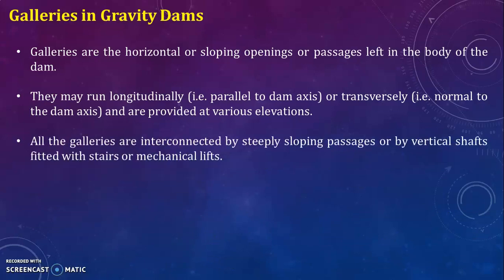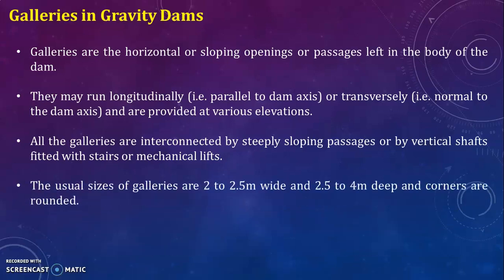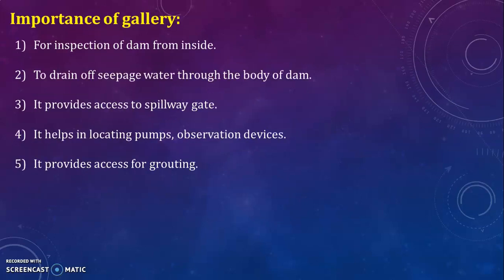All the galleries are interconnected by steeply sloping passages or by vertical shafts fitted with stairs or mechanical lifts. The usual sizes of galleries are 2 to 2.5 meter wide and 2.5 meter to 4 meter deep, and corners are rounded.